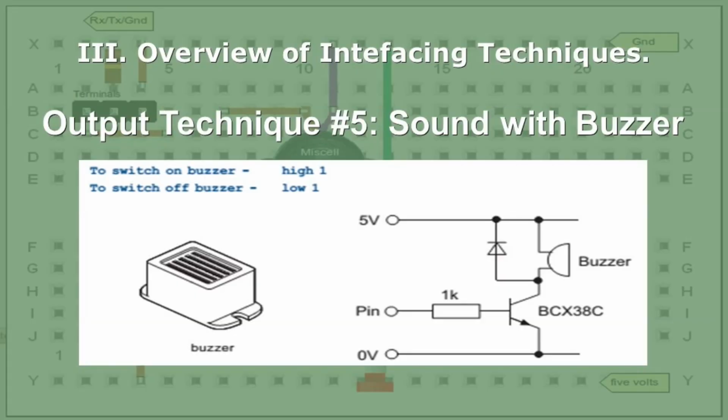Piezo buzzer. Notice the circuit is very similar. Your buzzer is in the place of the lamp. But you notice that diode across there. That's to prevent, when the buzzer quits sounding, a counter EMF from being generated and putting a spike through the system. Your microcontroller would not like it.